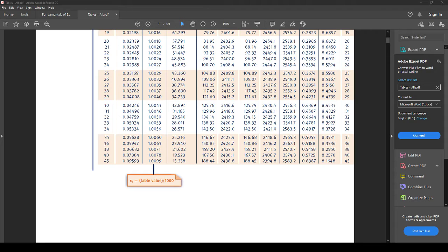But essentially, if you have a compressed liquid state, you can use this value, and I think it's this one, to approximate your answer for all three of these: v sub f, u sub f, and h sub f. You can use these three values to just say it's close enough, right?